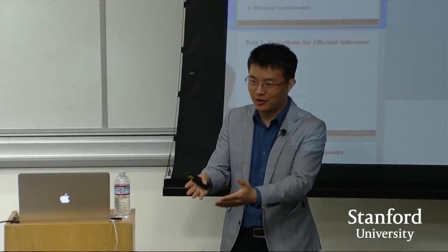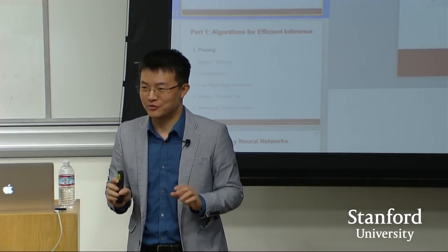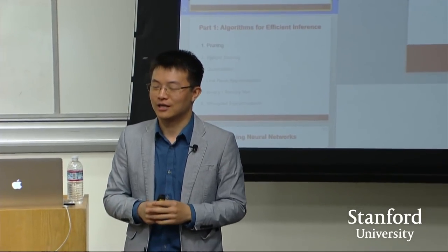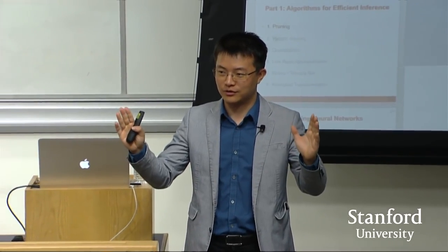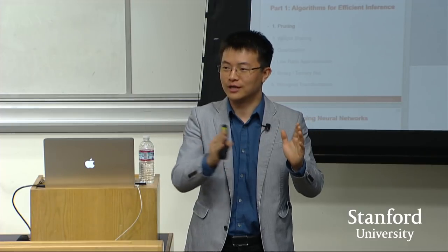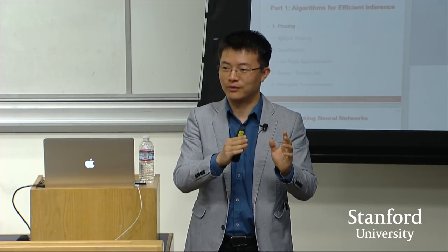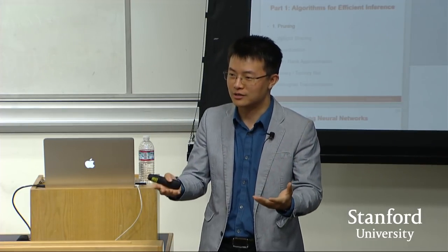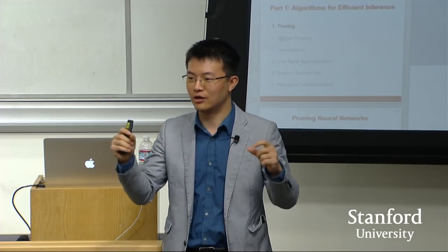Okay, the question is, if it's binary weight, the software developers may not be able to take advantage of it. There is a way to take advantage of binary weight, a paper called XNOR-Net. So in one register, there are 32 bits. Now you can think of it as 32-way parallelism. Each bit is a single operation.